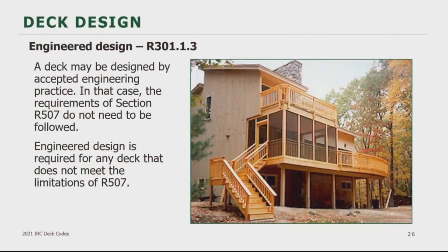If you want to design a deck that is outside of the scope of R507.1 or exceeds the limits placed on a deck in other places of this section, that deck would need to be designed through engineering. This could be due to the size, shape, materials used, or a number of other factors.